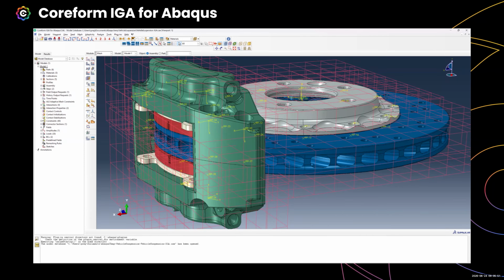In addition, you can use all of the traditional FEA tooling that you would use, like connectors, connector forces, and preloads, contact and assemblies that you already have experience with. I do want to mention that the red mesh that you see here is how we visualize our IGA meshes in Abaqus CAE today. Just to make this picture clearer, I've used a much coarser mesh here than we'll actually use for the solve, but so you can see the notion of what we're doing and why that simplifies the meshing process.